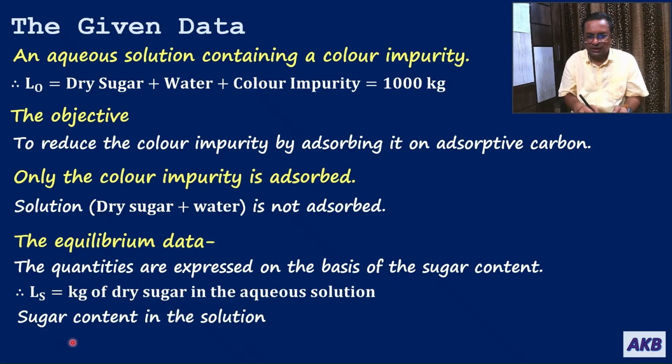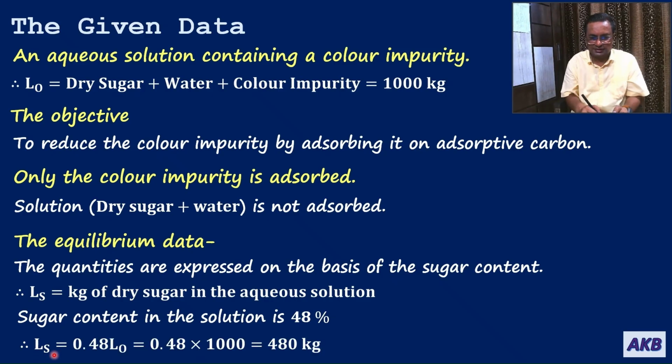So the sugar content of the solution is given to us. The aqueous solution is containing 48% of sugar in it. So we get LS. LS would be 0.48 times L0, which is 1000. So it is 0.48 into L0, that is equal to 0.48 into 1000, which is 480 kg.